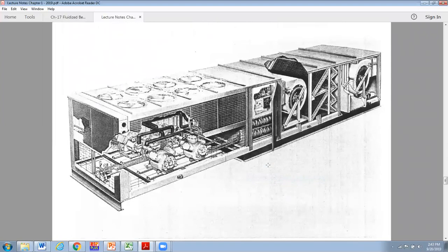This is a large package system. And so you see, we have kind of the condensing unit section that we had before on the large rooftop condensing section. But now we have fans, we have return fans and supply fans. This could be a power relief fan when you go on economizer. It can take the air from the building and just blow it out the back of the unit. And so this is the whole kit and caboodle. And these things can get pretty large.